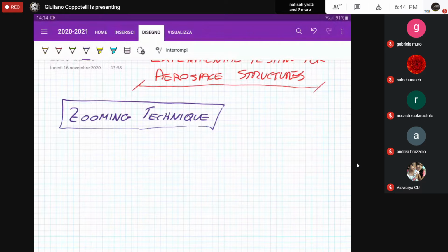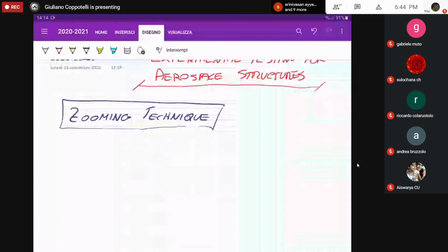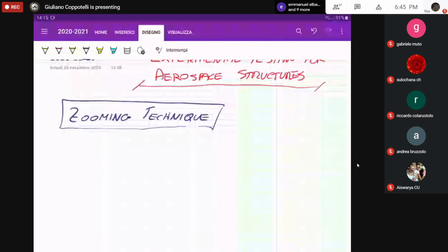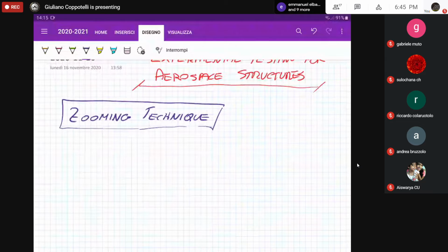we figure out that our chosen frequency range is not the right one, and specifically we would like to have more detailed information in a different frequency range with respect to the initial one. That's because maybe you were wrong in deciding the frequency range, or something happened that requires additional, detailed analysis. The main issue could be solved just by retaking the test. So we start from scratch, with all the acquisition parameters in terms of sampling points, frequency range, and check the new windowing functions and so on.